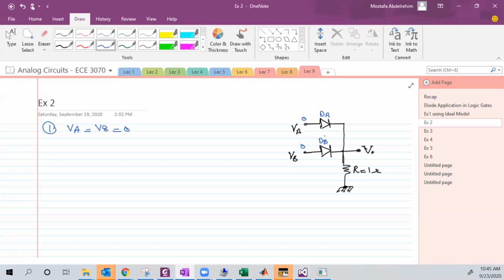What will be the situation or the condition for A and B, the diodes? Are they on or off when I put 0 and 0? They're both not conducting. Yes. And basically to conduct, you need a source, right? And remember, there is no source here. So everything is grounded. So from where will you get a current? These circuits are just, in some sense, passive. They need a source in order to give you a current. So basically here, both diodes are off.